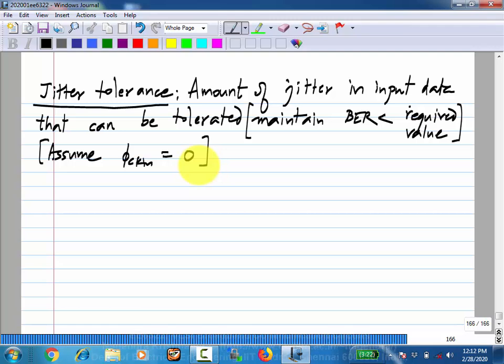Okay. Now how do you calculate this? First we assume that the timing of the clock with respect to data, that is phi d minus phi ck, should ideally be 0. This is the increment over the operating point. At the operating point, the clock is in the middle of the data, and now this phi d minus phi ck represents the skew in the data relative to the clock. This is the relevant thing, right?